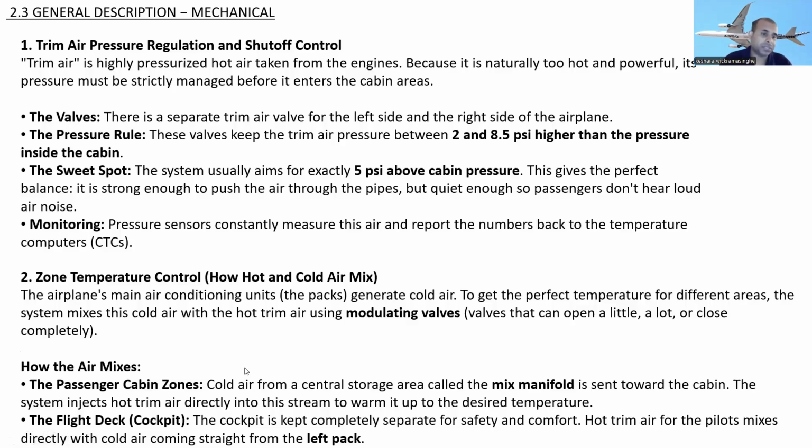How does the air mix in the passenger cabin zone? Cold air from the central storage area called the mix manifold is sent towards the cabin. The system injects hot trim air directly into the stream to warm it up to the desired temperature.